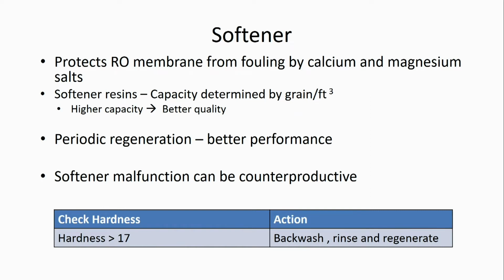Although we are regenerating it regularly, we should also look for the performance by checking hardness. If the hardness of water after softener is more than 17, then we have to do backwashing, rinsing and regeneration again.